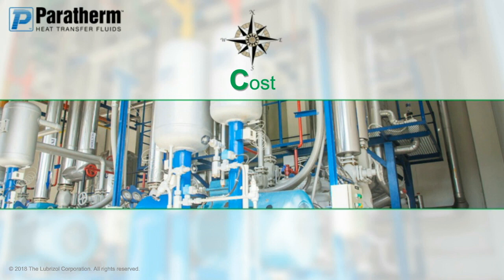What's the top-up rate that they recommend? If you're switching to a supplier that requires a 20% a year best practices top-up rate, that's going to come at a cost. Do you really need to do that, or should you just say, I would rather have my fluid analyzed and make my decision on top-up rate or switch-out rate based off of that?